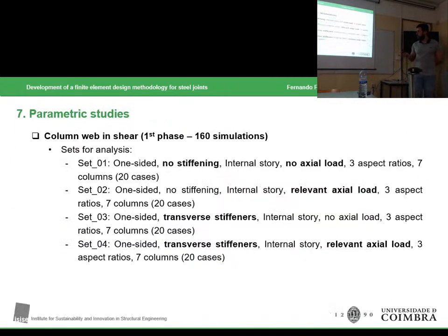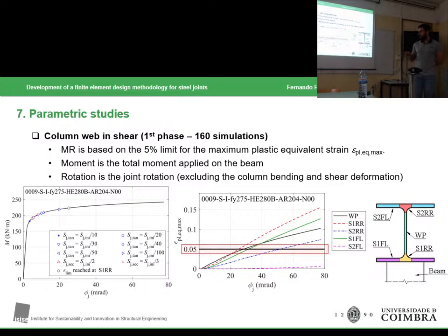And actually on this plot, you have a comparison between different values. So we have a fraction of the initial stiffness, the comparison between this value, the 5%, and the second stiffness. So the values do not differ too much in terms of resistance. In terms of rotation, there's a large difference, but in terms of maximum value, so for the load, it's below 5% generally.